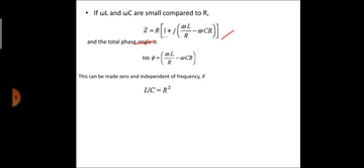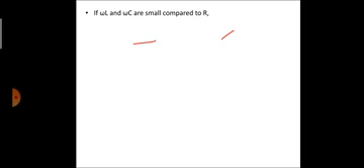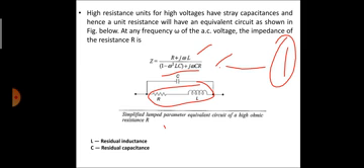Now, if the resistors which we are using here are large, for extended and large dimensioned resistors this equivalent circuit is not valid. Each elemental resistor has to be approximated with this equivalent circuit, so the entire resistor unit has to be taken as a transmission line equivalent for calculating the effective resistance.